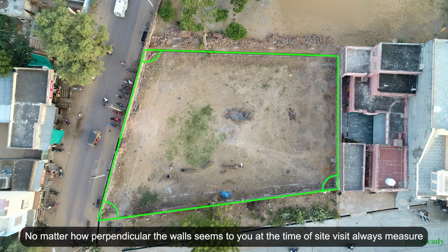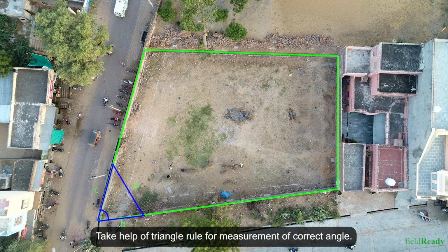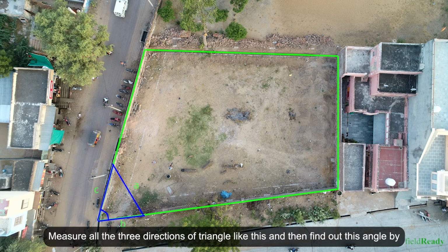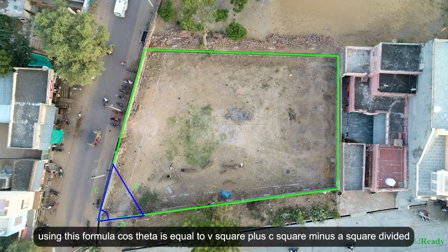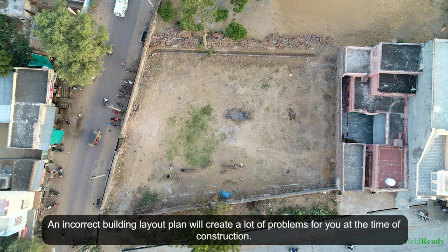No matter how perpendicular the walls seem to you at the time of the site visit, always measure the angle between the property lines. Take help of the triangle rule for measurement of the correct angle. Measure all the 3 sides of the triangle like this and then find out this angle by using this formula: cos theta is equal to b square plus c square minus a square divided by 2bc. Without the correct angle, you will not be able to draft plot plans correctly in AutoCAD. An incorrect building layout plan will create a lot of problems for you at the time of construction.